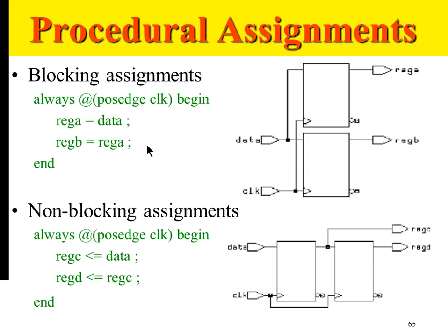So it means that for a combinational circuit that does not require any clocking, blocking assignment will be good. Yes, you're correct. Non-blocking is for sequential circuits where flip-flops are considered. For combinational circuits, there is no clock required. In such cases, blocking assignments are okay.